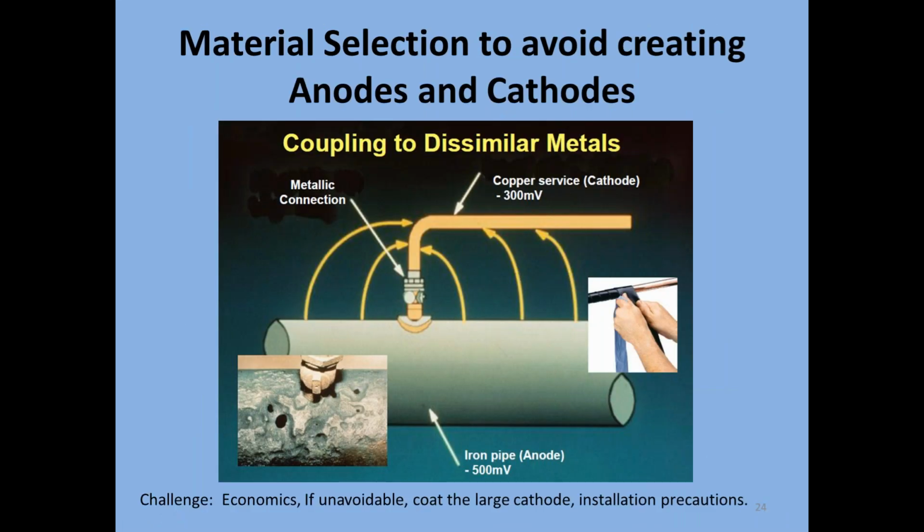So this is probably, when it comes to the majority of corrosion problems out there, because of dissimilar metal couplings that are not compatible, or just forgetting that there should be a dielectric union between them. A dielectric union is a piece of plastic or something that doesn't allow electricity to flow through. Right? But that is the largest portion of all the failures out there. This is an example of copper connected to a steel iron pipe. See, the copper is much more noble than the iron. See?